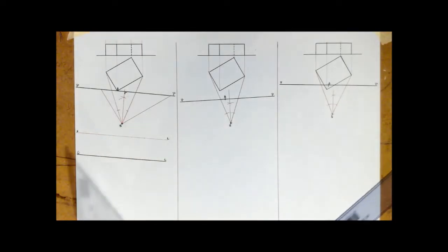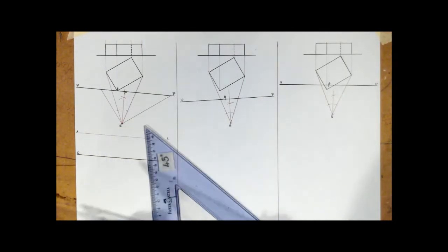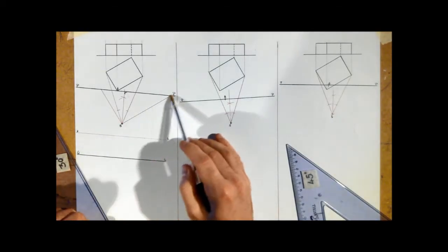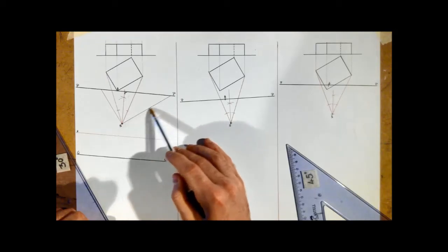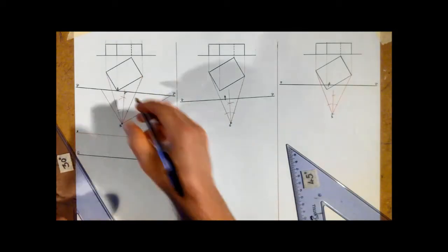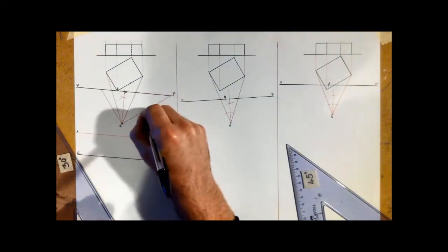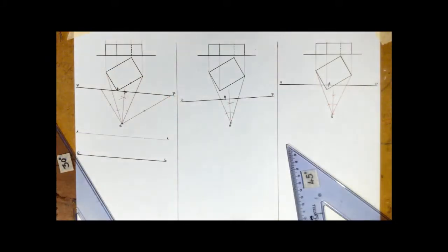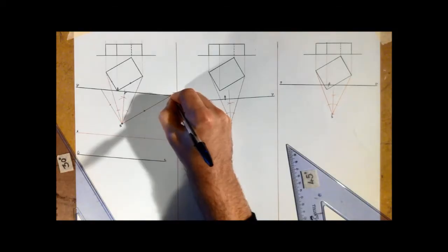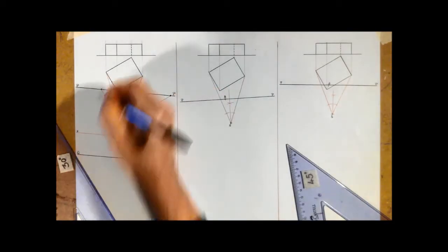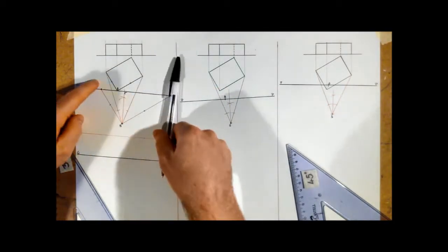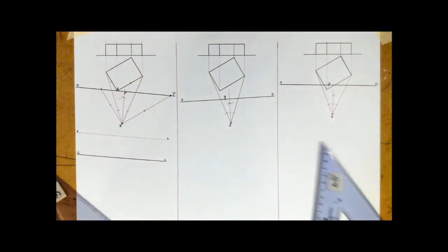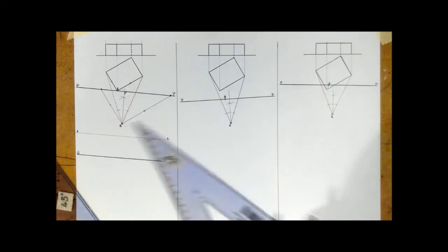Okay, and to locate the vanishing points, this is very, very easy at this point now. The vanishing points, if you can remember, from the spectator, we went parallel to the edge going this way. Okay, so I'll just put in that there, and this edge was this way. Now, at these points here, here, and here, we are going to drop them down perpendicular to the picture plane to hit the horizon line. Okay, and that will be where our vanishing points are.